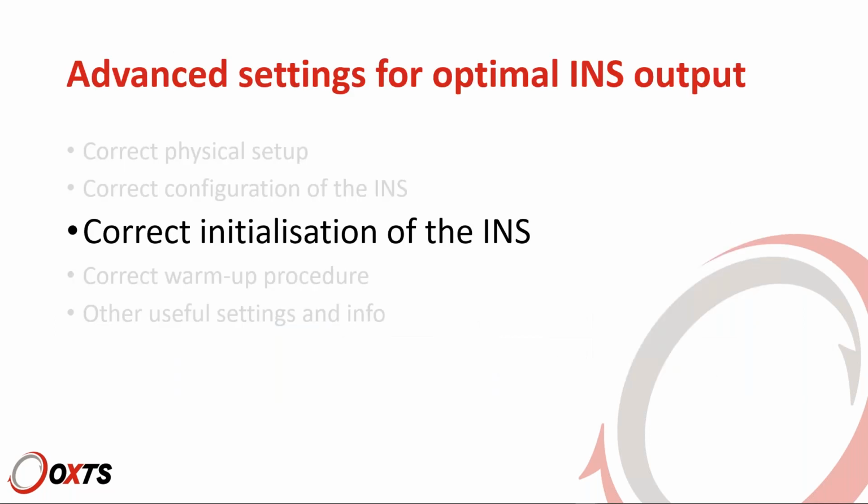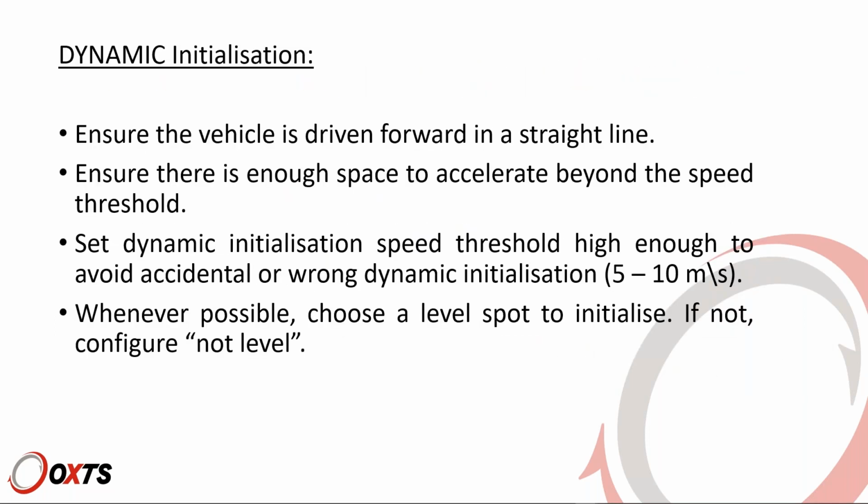Okay, initialization. Initialization is basically about getting directions right, literally. On a land vehicle, it's fairly easy to get it right. All you need to do is drive forward in a straight line. The thing you have to be aware of is to have enough space in front of you so that you can accelerate to reach a speed threshold that will allow the system to initialize.